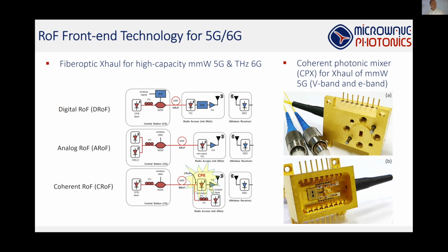And since we are using two anti-parallel photodiodes, we are suppressing the DC noise. So this is a system which is very much suited for wireless applications because it suppresses the DC noise due to the balanced photodetector application. If you are interested, I can forward you some more technical data on how this works. So in general terms, it's called optical heterodyning and balanced photodetection in order to upconvert, or to convert, from baseband optics to RF.